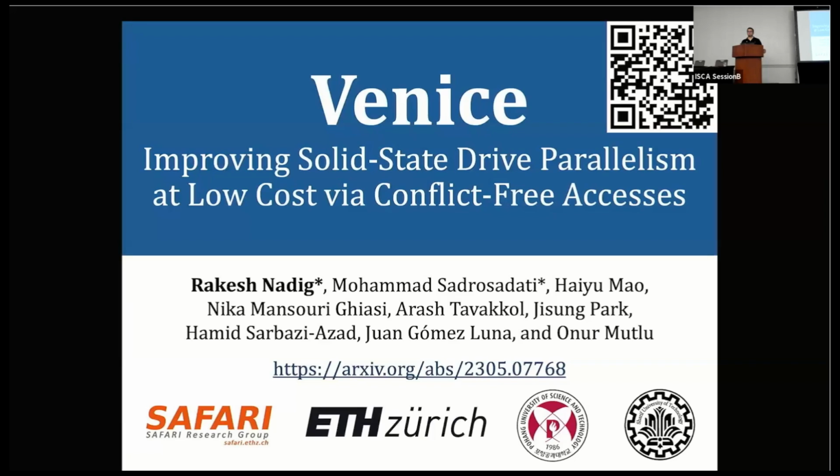Andreas Koch, Darmstadt. Can you give a rough impression of the relative times required for the path reservation step and serving the actual request? From our experiments, the path reservation step takes around 40 cycles at max, so around 40 nanoseconds, compared to the actual IO transfer, which for a 16 KB page takes around 16 microseconds. So it's an order of magnitude less than the actual page transfer. Thank you.